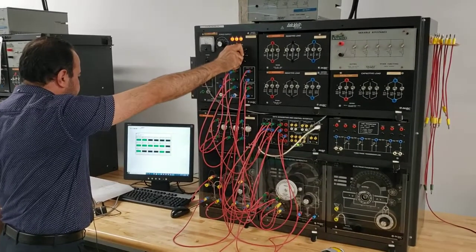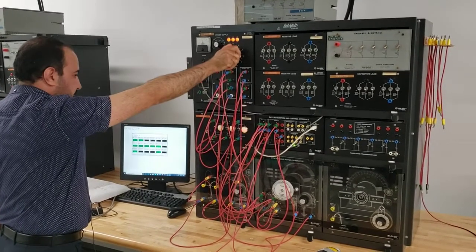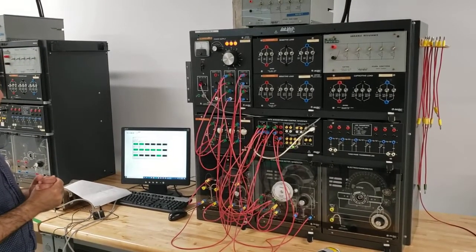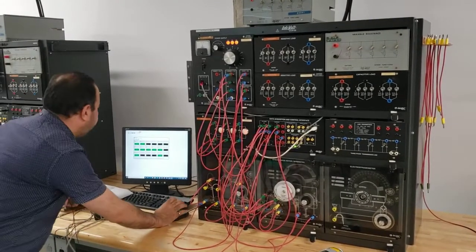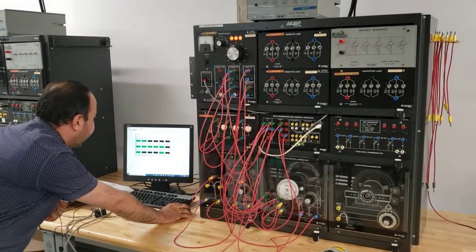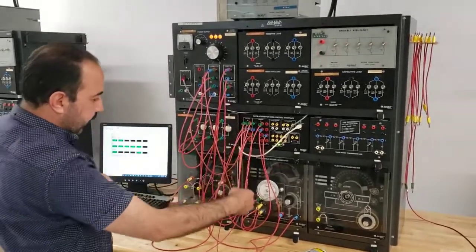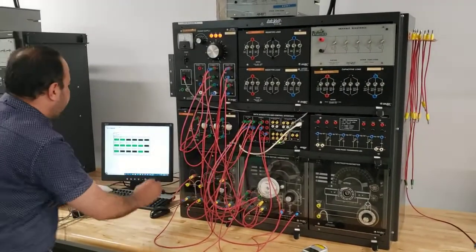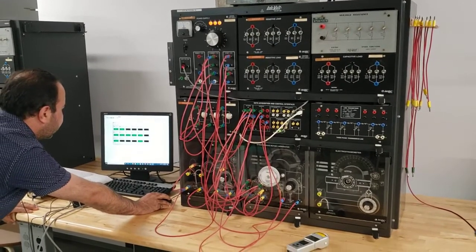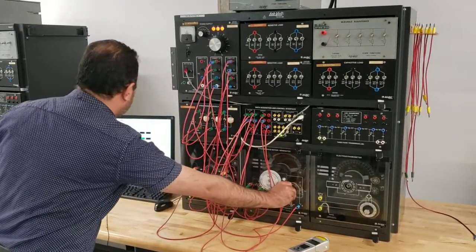Here, I'm measuring the phase voltage. The voltage that I have right now is 108, almost 110 for the grid. But the problem is that I have a difference in voltage between E1 and E2. E1 represents the voltage for the synchronous generator, and E2 represents the voltage for the grid. The grid is 120, but the synchronous generator is 108. So I can adjust this by changing the field for the synchronous generator.